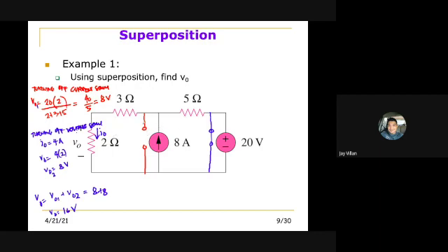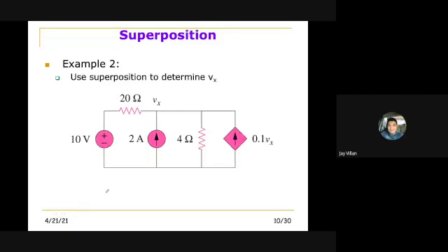And since that is the direction of the current source, then here at the top, this is more positive than this here, because the direction of the current was dictated. So it is the same direction as when the current source is turned off, or when the 20 volt source is acting alone. Therefore, they have the same polarity, so we add them. Okay? So, that is the superposition formula.